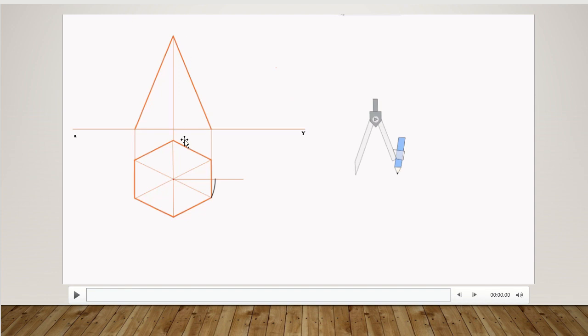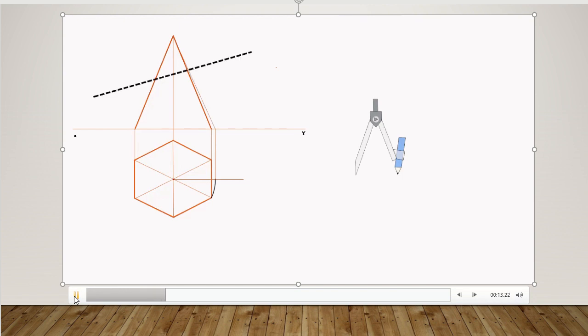Now the basic important thing is you have to draw a horizontal line from here, after which take this radius and create an arc. Now project a line from this point to the XY reference line, as you might see in the next step. Just hold on. You can see it. A line will be projected to the XY reference line, after which you have to join the top point to this particular point. Yes, you can see a light line joining the top and this point.